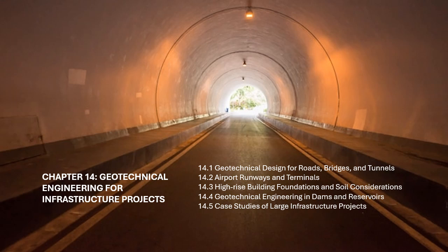In cities where soil may vary greatly from one area to another, mat foundations are used to distribute loads more evenly and reduce the risk of uneven settlement. These foundations can be designed as reinforced concrete slabs that cover the entire footprint of the building. Spread footings. In some cases, individual footings or pads are used beneath columns or walls. Spread footings are effective when the soil has sufficient strength to support the building's load.